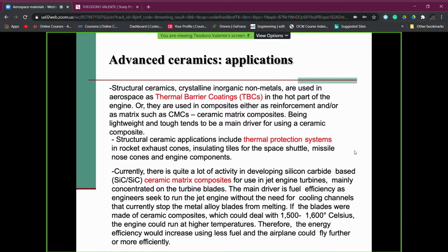The first one was recalled many times, and today we will put online some concepts in order to let you remember well the importance of the so-called thermal barrier coatings. Thermal barrier coatings are used as coatings in the whole part of the engines, and usually they belong to the class of the oxide ceramic materials.